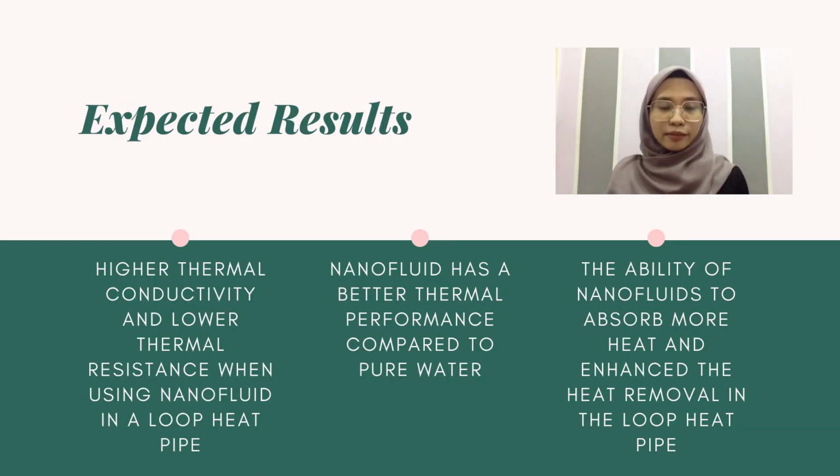So this is the expected result. At the end of this study, higher thermal conductivity and lower thermal resistance are expected when using nanofluid in a loop heat pipe. The simulation result will indicate that the nanofluid has better thermal performance compared to pure water. The higher thermal conductivity is due to the ability of nanofluid to absorb more heat and enhance the heat removal in the loop heat pipe. By using nanofluid as the working fluid, the thermal resistance will be lower than using pure water. The evaporator temperature will increase when using nanofluid and attain steady state faster compared to pure water.